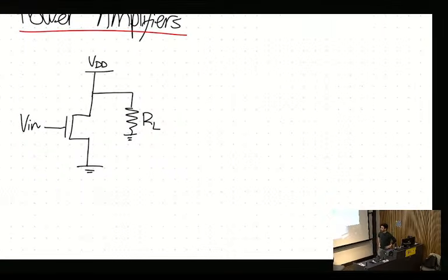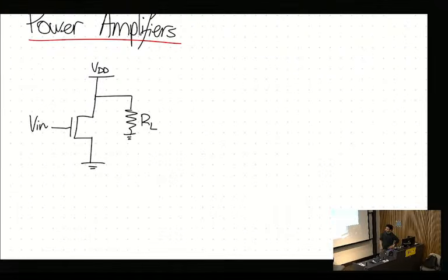The role of a power amplifier, it seems obvious, is simply to increase the power of the input. And the way it does that is effectively by flicking this NMOS off and on. The input signal is controlling how much power we're drawing from the power supply at any given moment, so the amount of power we're drawing, IL.